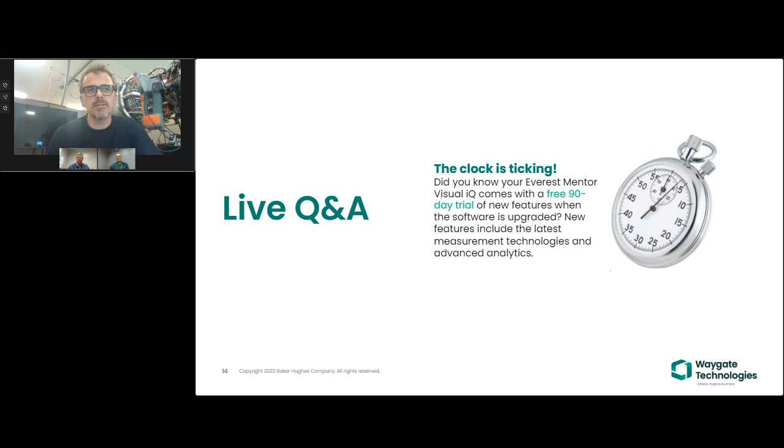And then from a software perspective, make full use of the tools that you have on the boroscope. Number one is the brightness setting appropriately configured. Obviously, putting it too bright might over-illuminate and overexpose some of those target surfaces that you're wanting to look at. So make use of some of the tools and tips that you heard in webinar number 1 last week that talked about probability of detection.